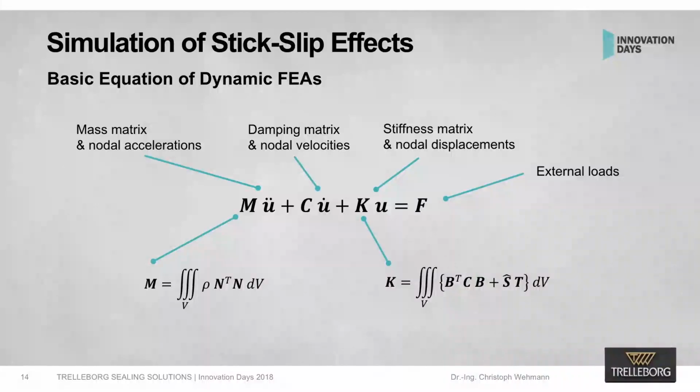So now we have to also look at the inertia forces, which are given through the accelerations of all nodes in our model, and we have to also look at the velocities here. U means the displacements, U dot is the velocities, and U double dot the accelerations. And we have to consider the mass matrix here. So the density also plays a role to clarify the inertia forces.